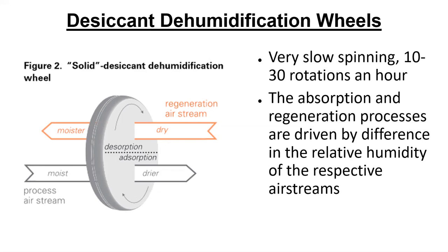See, the other way that we get moisture out of an airstream is we just make it really cold. We put it across a really cold cooling coil, and then the moisture condenses out, and then the air might be too cold, and then we have to heat it back up again. So there are two energy expenditures. First, you had to make your chilled water or your DX system produce very, very cold air to get the moisture wrung out of it. And then you had to somehow heat it back up again so that you don't freeze the poor people in the space. So that's what we're comparing and contrasting to here.